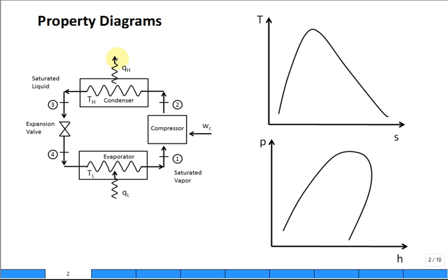So what we have is the standard setup for vapor compression refrigeration. Saturated vapor at state 1 is fed into the compressor. It's superheated vapor. It comes out of the condenser as saturated liquid. Then it goes to the expansion valve. It flashes through the expansion valve and then evaporates in the evaporator. Well, on a TS diagram, we've seen this, have we not?